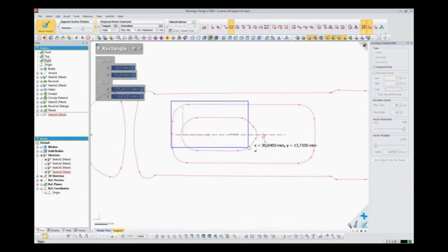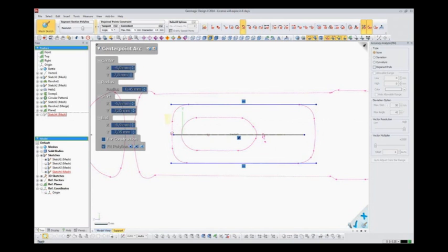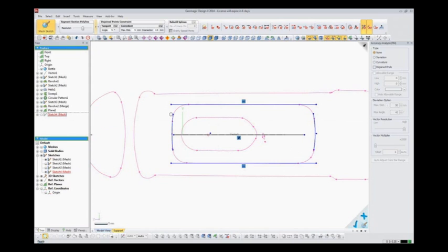And now I'm just creating maybe a box around it. Convert this as a middle line. Okay, I will replace the upper and lower part with arcs. So that will be an arc, and that will be an arc. Those arcs will be equal radius. Oops, equal radius. So I'll just move it around.